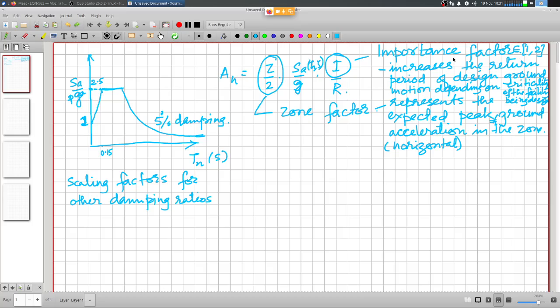So intensity of ground motion changing by a factor of 2 is a very major scaling up of the excitation, and an importance factor of 2 effectively corresponds to designing the facility for the largest possible earthquake that we may expect to take place in that region. So obviously importance factor of 2 is reserved for facilities which can have very disastrous consequences of failure, which are required to be functional even during the worst possible scenario.